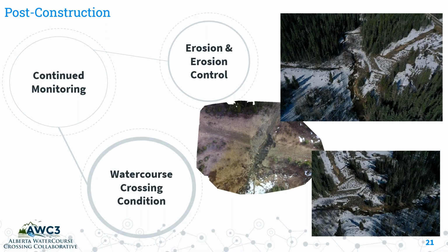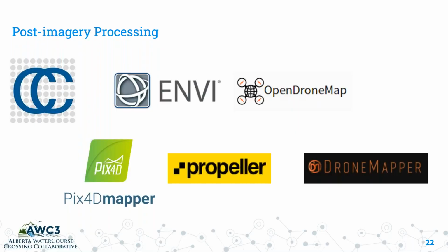You could also do a seasonal assessment where you go, okay, we can see that our culvert that we installed here is not restricting water flow through the area and therefore increasing the water flow through a culvert and causing a physical barrier for fish during the springtime. You could also use this as just continued monitoring afterwards.